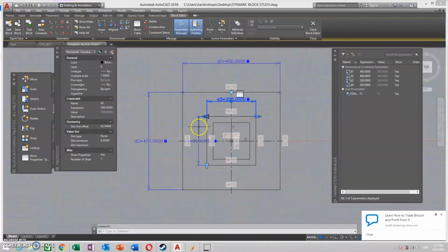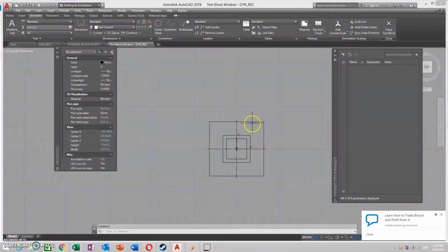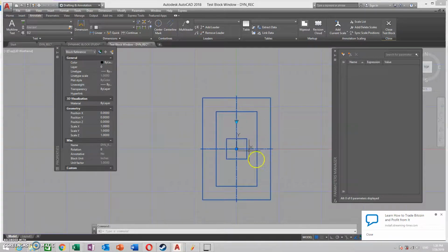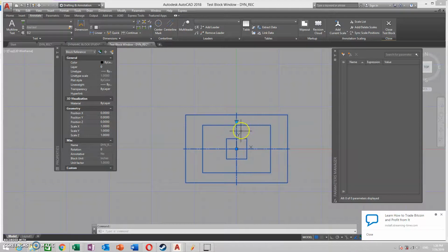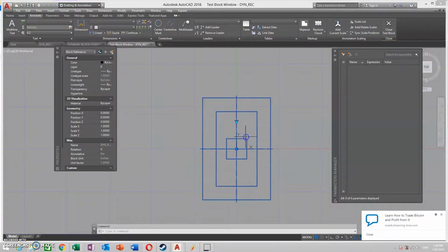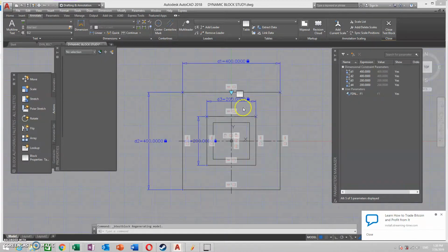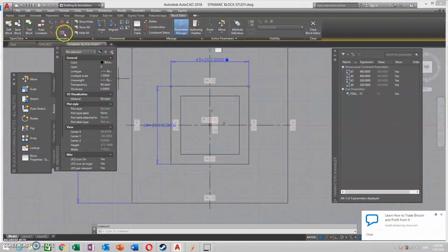So now we'll turn off the grips. Make it 0, then test the block. Check type 2, see now the footing size also changing. Type 3, now only the last one, base plate, then the bolt holes. So okay, go to type 1, type 2, type 3. Okay, just close the block editor. So mostly we need to repeat the same. Same here. Symmetric, and 2 dimensions.